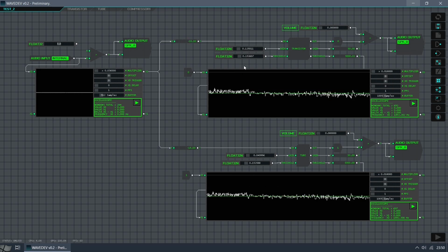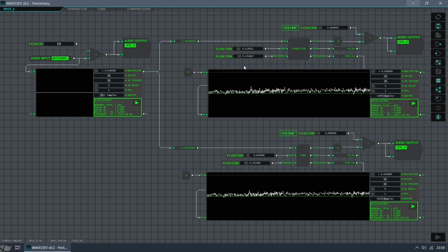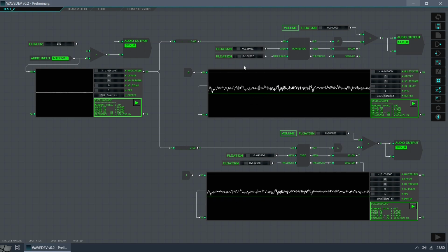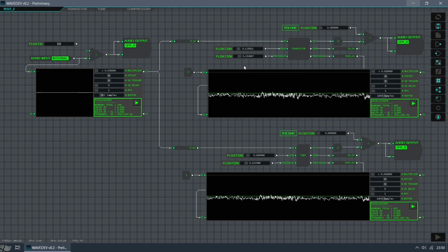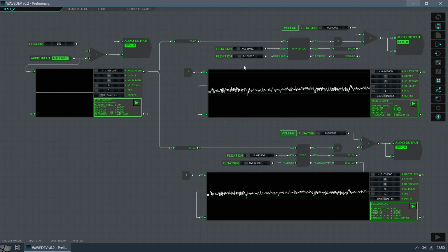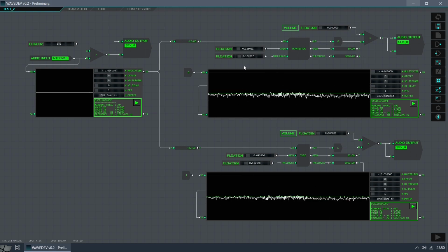But this should not surprise those who have already experimented with this type of distorting functions. I'm applying much of what the literature indicates about this effect. What is not said is that saturation cannot be applied to all the components of the signal. As we increase the gain, the first components that saturate cancel the rest, and these are irrecoverable. In the natural signal, the wrong components saturate first. So we must adapt this signal to first saturate the right components. We have some filtering work to do before going into the amp.